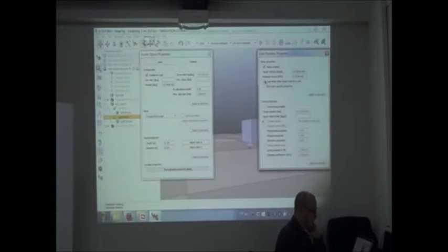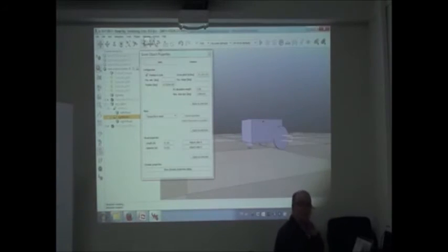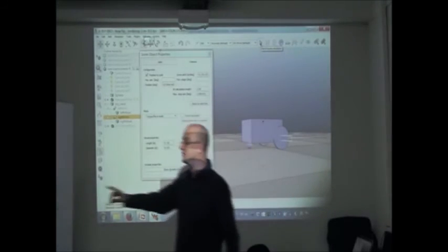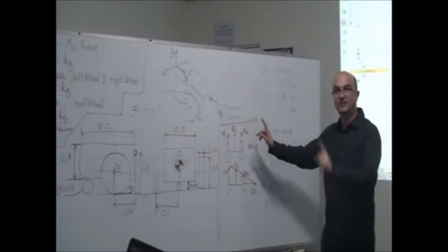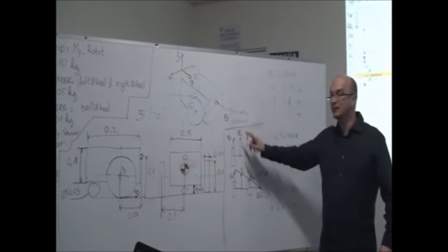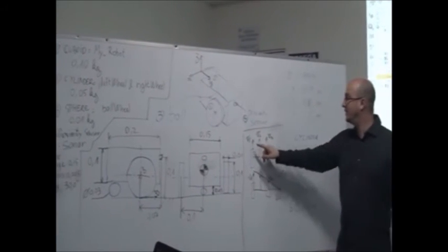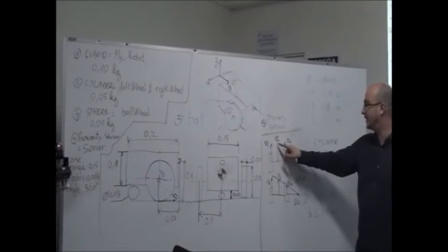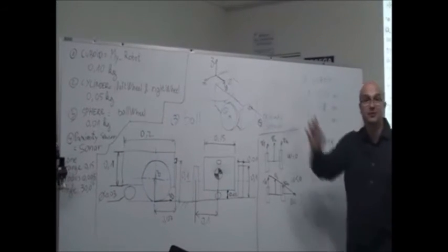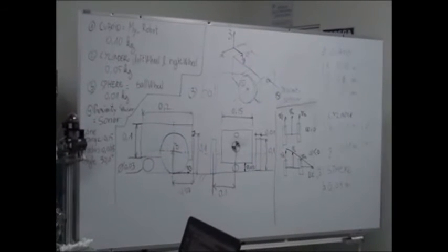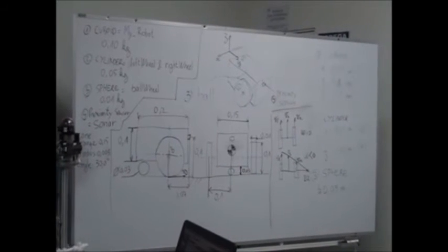Motor enable, lock if 0, and 10 degrees per second. Okay? Now what will happen? What do you think will happen? Yeah, exactly. The robot will go front, because this is the model that Andres showed: if we put left velocity and right velocity the same, we have the linear velocity, which is the average of both, VR plus VL divided by 2. So the robot will go straight because of the same velocity on both wheels. And exactly what will happen is what you said, I guess.